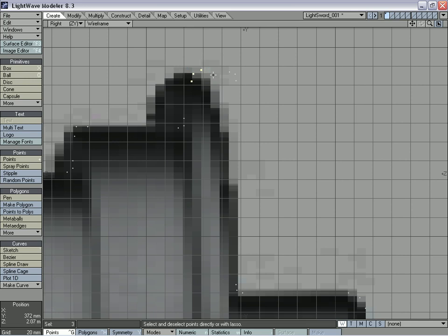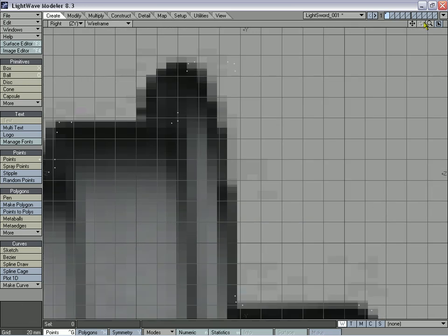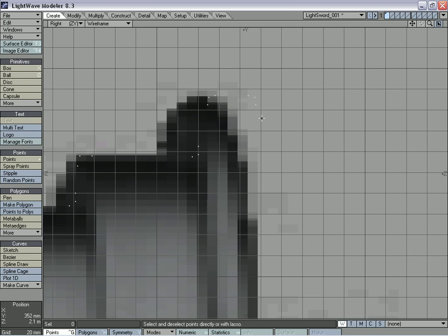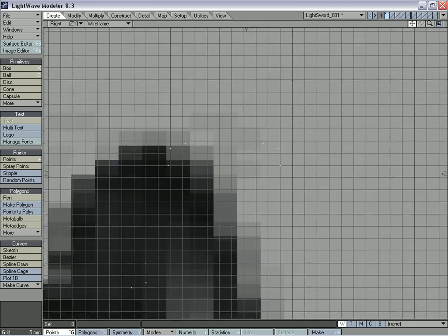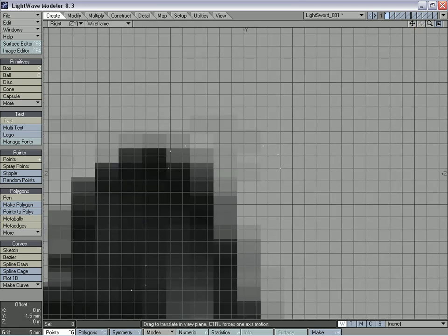And actually, for these points, we can just delete all three of them and use these ones and mirror them. Do that by using Shift V and then just left mouse clicking about in the center of where you're going to want it, and just pull it down a little, and then you'll get your mirrored points. And actually, it looks like we need to pull these down just a little. So I'm also using the drag tool again, which is Control T, just to pull these down.